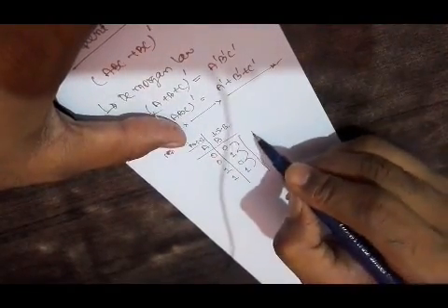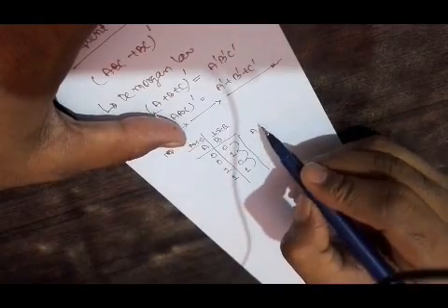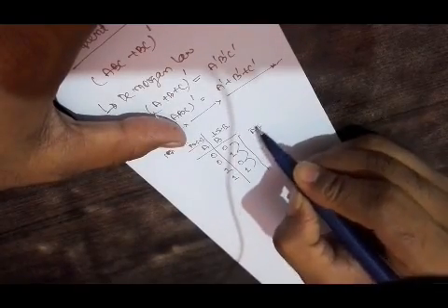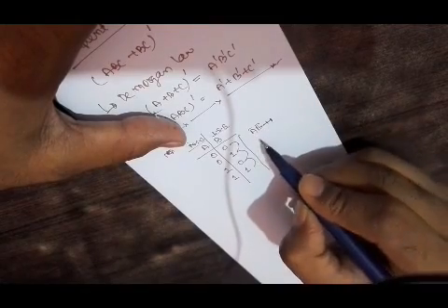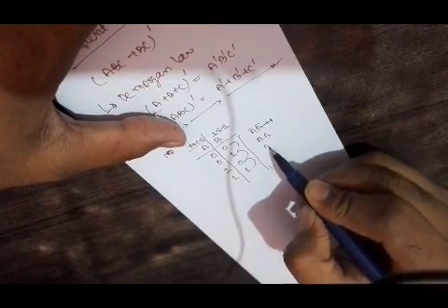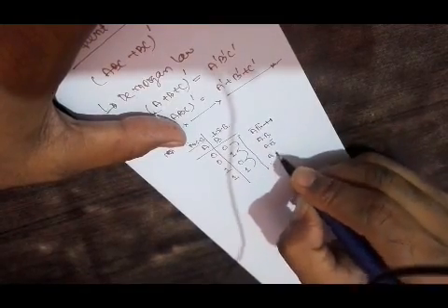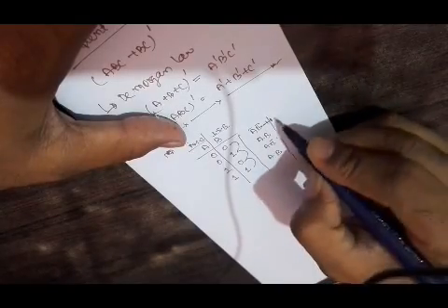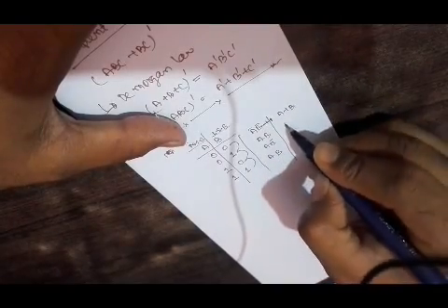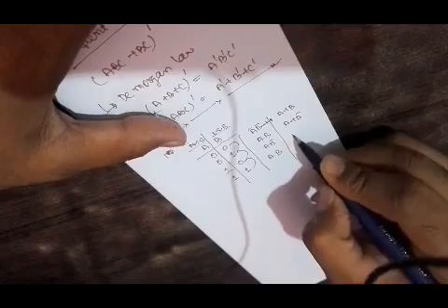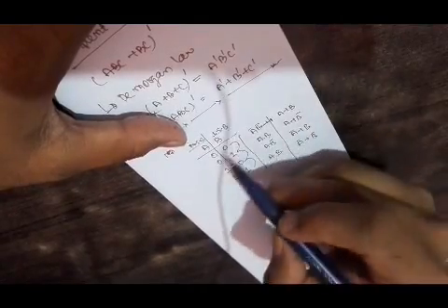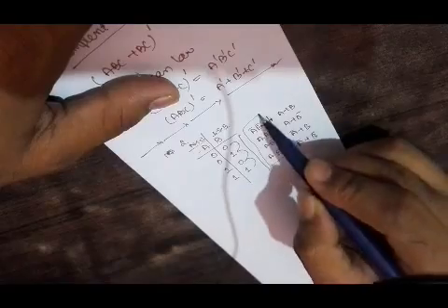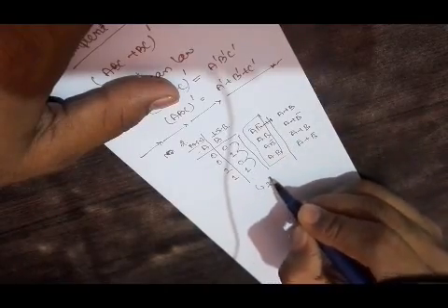And then if you want to convert it into the sum of product or product of sum, just write a bar b bar plus a bar b plus a b bar plus a b, right? For product of sum, this is a plus b, this is a plus b bar, this is a bar plus b, and this is a bar plus b bar, right? For two variables, we have only four possible terms, that can be written as 2 raised to the power 2.